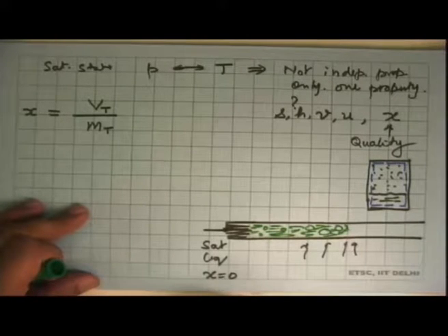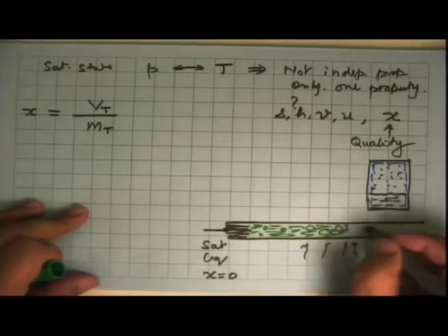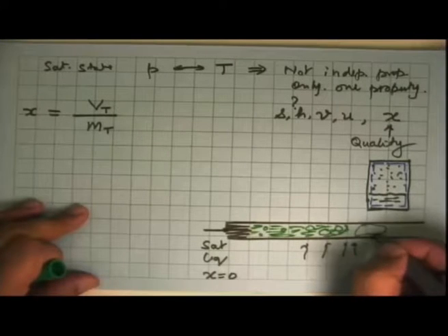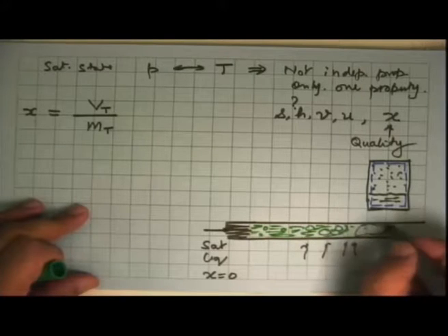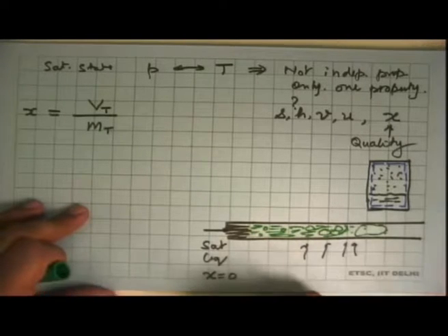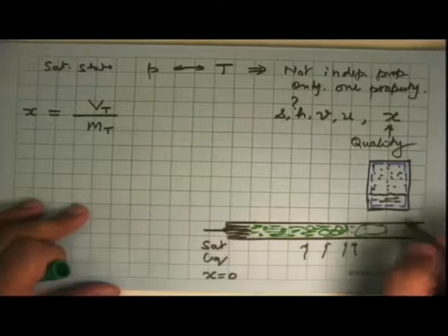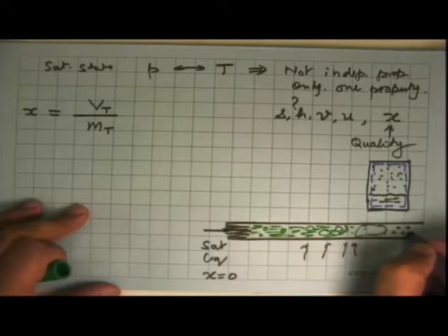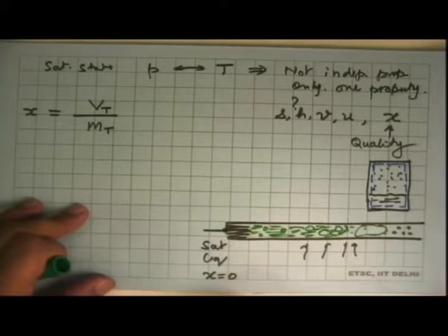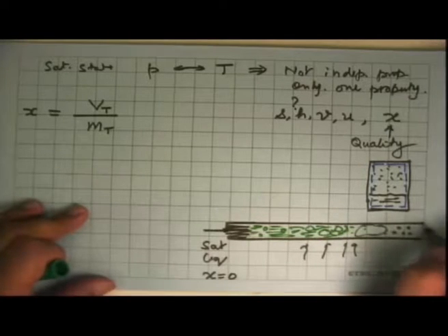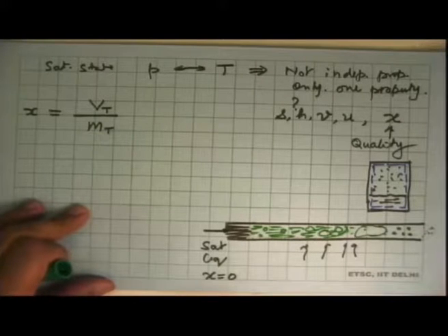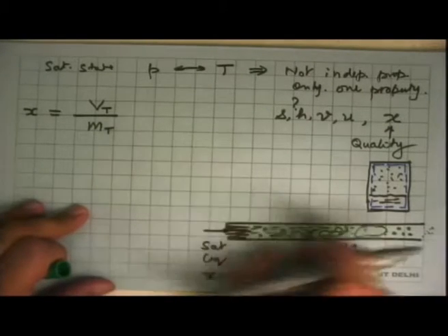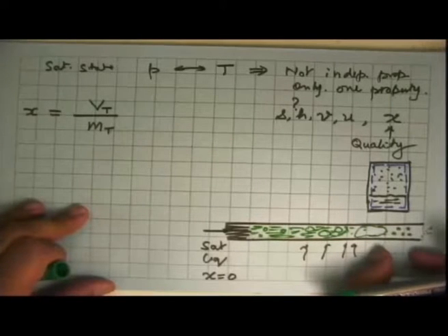And when even more heating takes place, these bubbles start to occupy a larger space in the tube, and the liquid is now in smaller amounts in a very irregular fashion. And then we could have a state where there is lots of vapor, small amounts of liquid as fine droplets, and finally only vapor. So physically this is what happens in the tube.